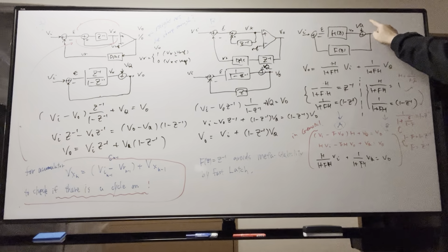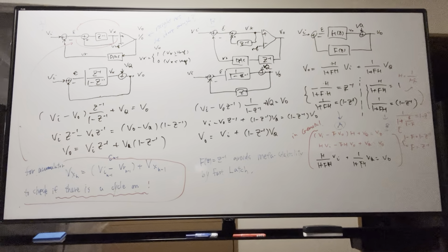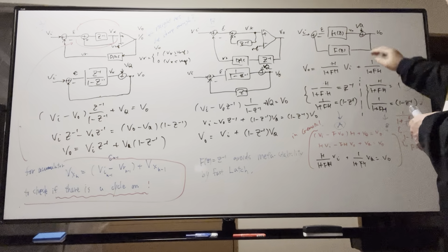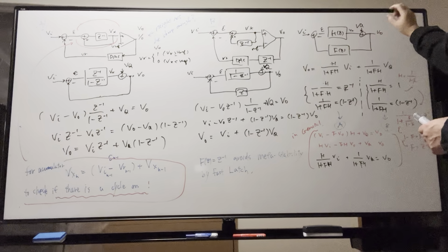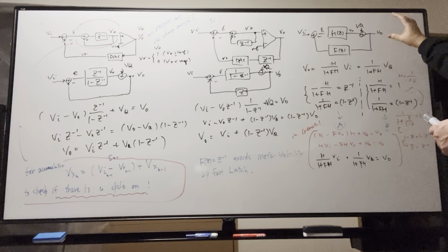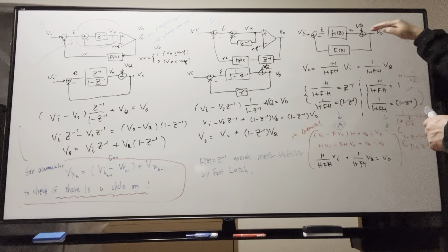VQ is a quantization noise added at the output comparator. And so we need to accumulate the value to a 1 or 0 bit value judged by the reference voltage.